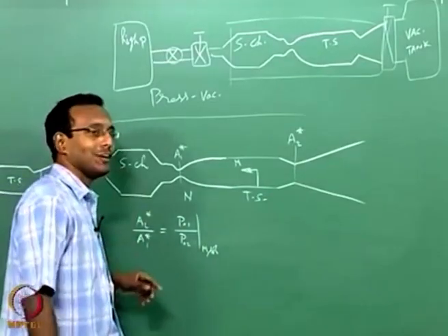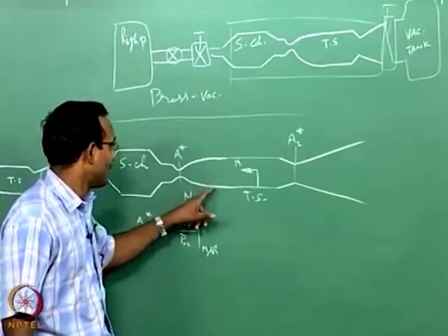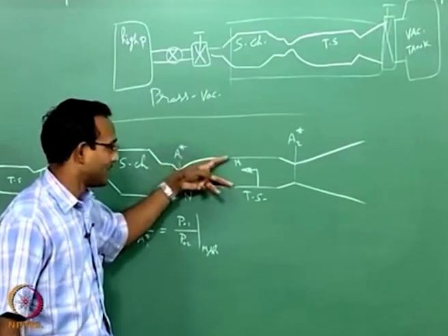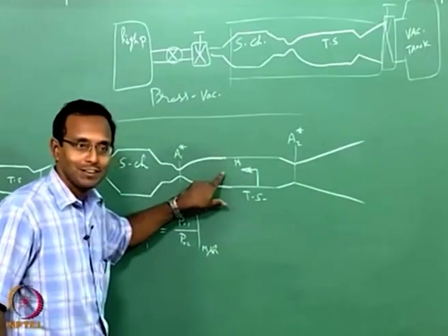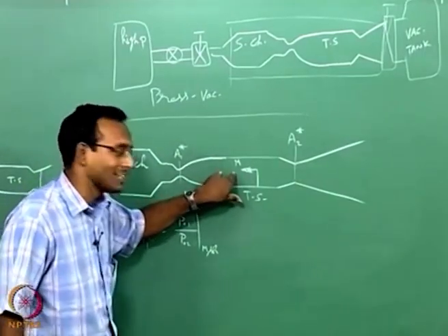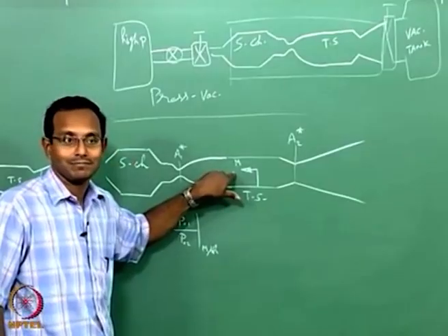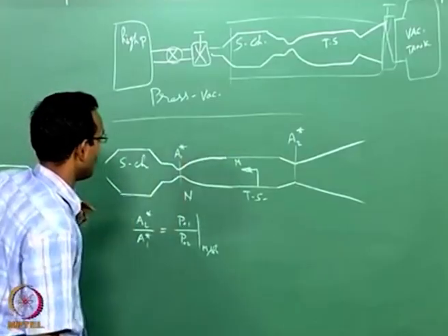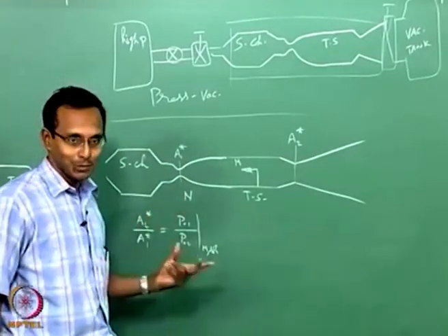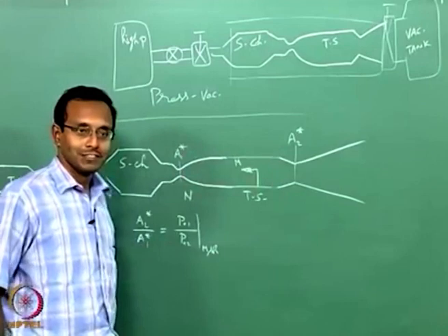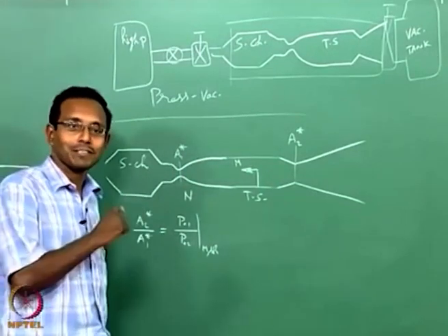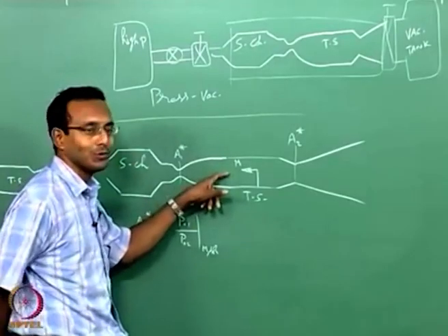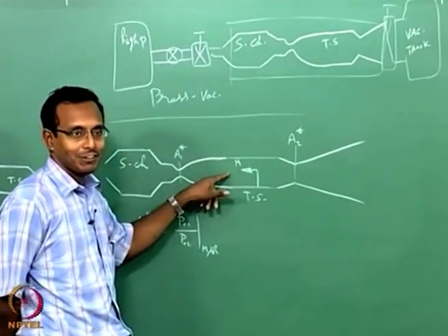Okay. Typically to avoid this problem, what they do is they make this nozzle such that it is almost flat, parallel towards the end, and they put the model in here itself. Then the nozzle end point itself becomes your test section. That also people do for decreasing cost, of course. But a cleaner experiment is when I have this straight section where I want to make sure the Mach number is constant everywhere. That is better. Okay, but of course my assumption is not true if I say friction is not here.